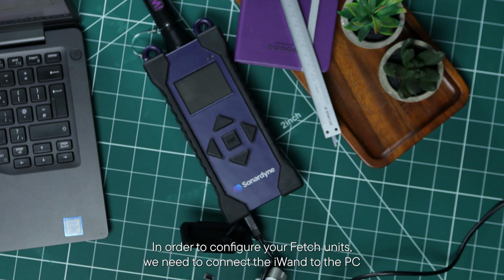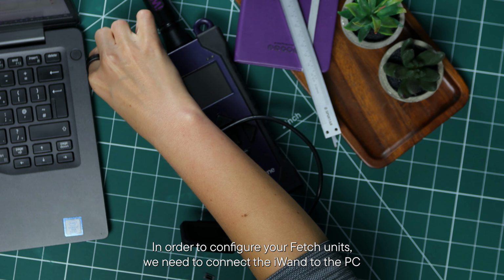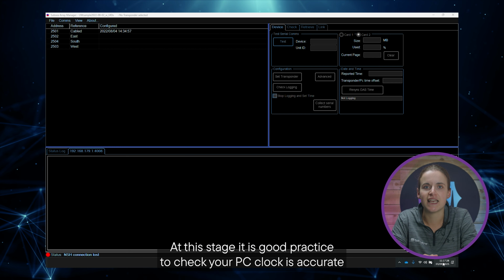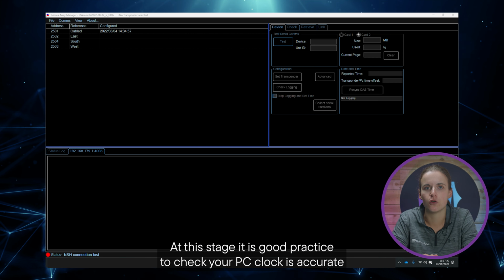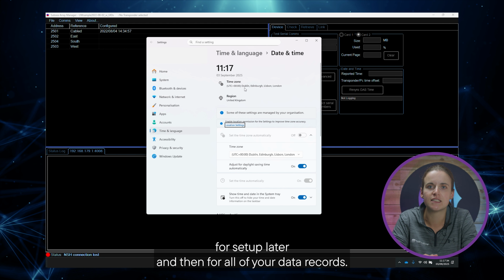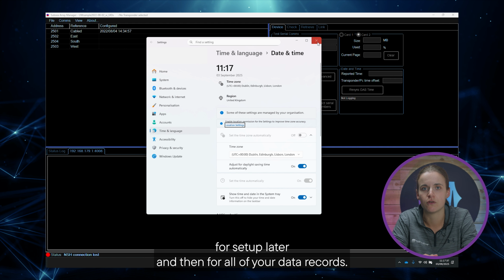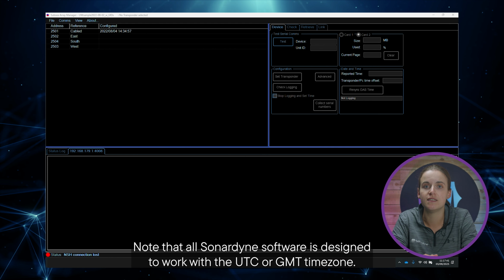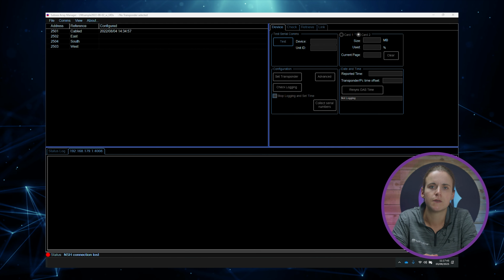In order to configure your fetch units, we need to connect the iWand to the PC or laptop. The easiest way to do this is via USB. At this stage, it is good practice to check your PC clock is accurate and that the correct time zone has been configured, as this is important for setup later and then for all of your data records. Note that all Sonardyne software is designed to work with the UTC or GMT time zone.